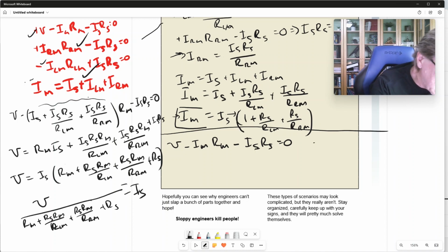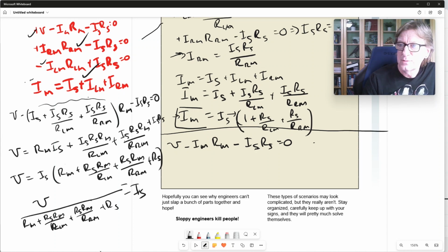That's the current that's going through the sensor right now. Okay, so now you know all of these values. I'm not going to take the time to multiply them out, but you know that the voltage is 5, and we know the resistances for all of these. And you should find that IS works out to be 2.63 milliamps. Let me write this over here a little more neatly.